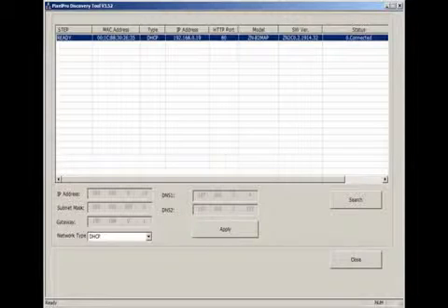First, check and confirm the camera is getting power. This can be confirmed by way of a solid green LED on the camera. If the camera is confirmed as getting power, then the next thing to check is any running firewall program on the PC. Be sure to turn off any and all running firewalls on the PC in question. Third, check Cat5 cable for any damage. If a switch or hub is used, check for a possible bad port by moving the camera and or PC over to another port.